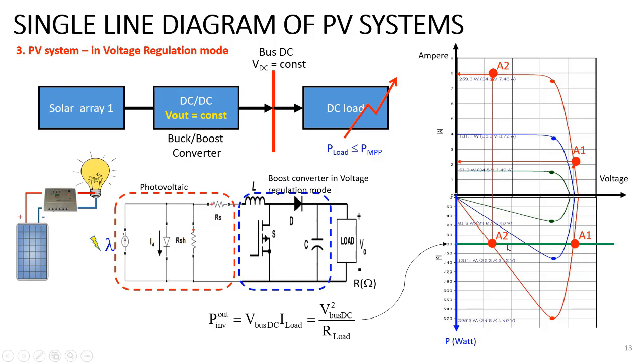Look at the point A2. We may find that the voltage value is lower than that of A1, while the working current is around 8 amperes in comparison to that of around 2.1 amperes of A1. Obviously, for the same consumed power on load, the lower the working current is, the less power dissipation occurs in the system circuit. Therefore, for a higher system efficiency, the better selected working point is A1, which is always on the right-hand side of the maximum power point.